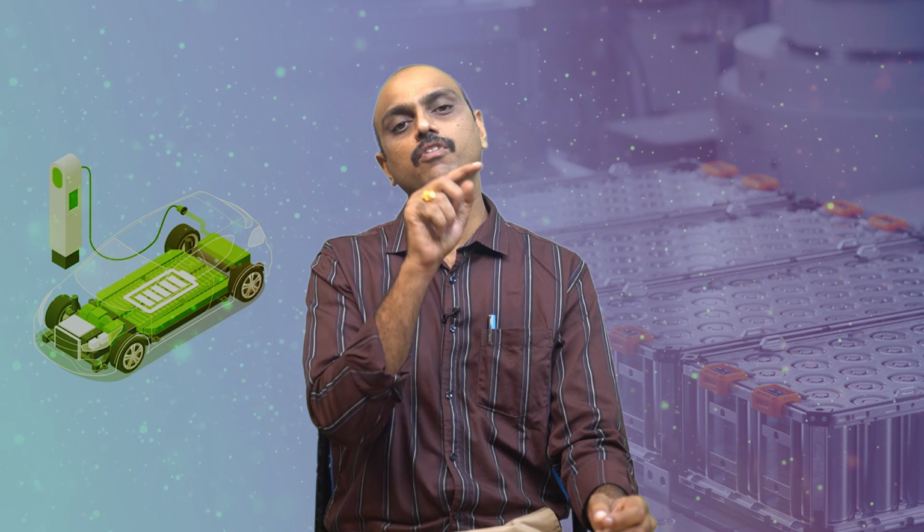You might have studied in the previous lectures, the battery will discharge with a constant current rate or a constant voltage rate. Same way it will charge through the constant current rate or constant voltage rate. Now, when it is charging through the constant current rate or the constant voltage rate, we need to see the optimal charge rate, which is 1 C, 2 C, half C, 0.25 C, whatever it is. So, that is one of the major operating conditions.